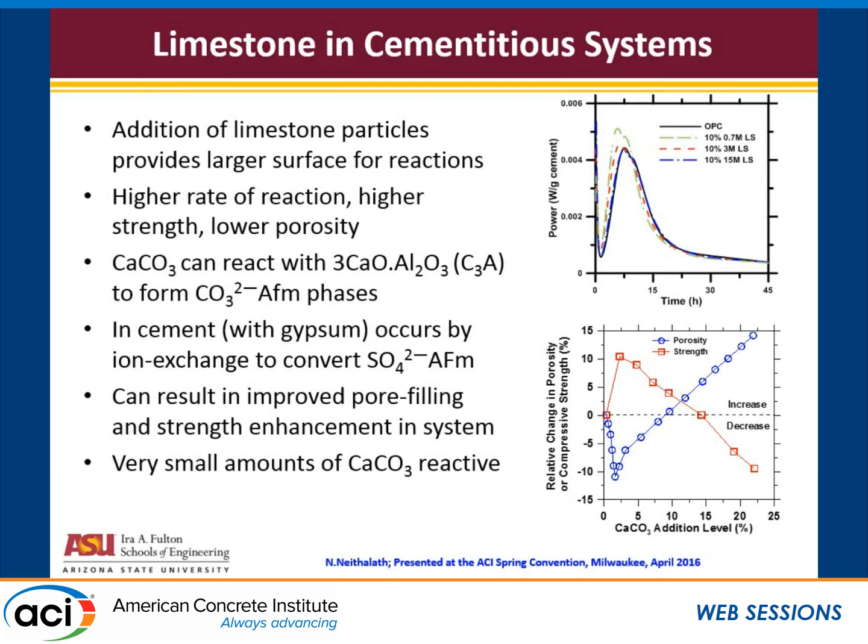If you have very small limestone particles, you have a lot of surface area for reactions. You will see that with limestone, the heat of hydration goes up. The same idea as the rate curve that Jason showed: you will have a higher amount of heat. Now, where is that coming from? You have a higher rate of reaction because all these very small limestone particles are making your cement hydrate better, because these are also places for cement reaction products to nucleate. So you get more surfaces, more walls for people to lean on, more hydration products lean onto the walls, and are very happy with that. So that's what is happening with this higher rate of reaction.